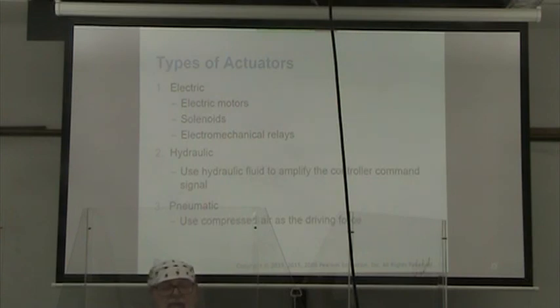All right, so we can have different types of actuators. We can have electric, where we have electric motors, solenoids, or electromechanical relays. Can be hydraulic, where we use hydraulic fluid to amplify the controller command signal, or pneumatic, which uses the same idea, where we use compressed air as our force.